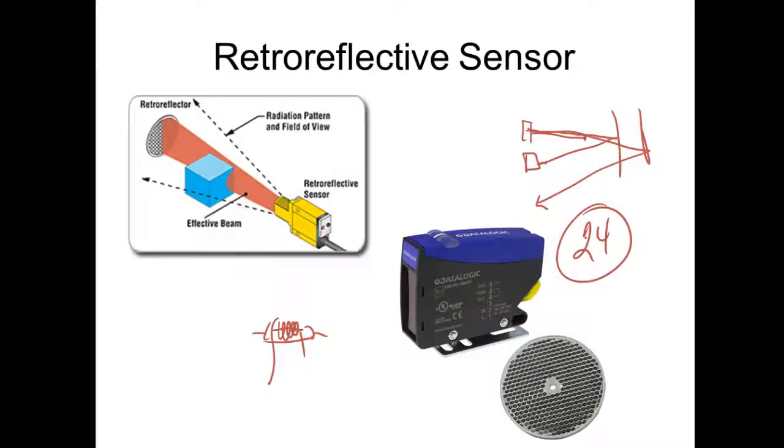Yeah, so on the Siemens, you can get relay outputs on Siemens PLCs. It's just that the ones that they got here are in a 24 volt system, so they just bought 24 volt outputs. The Allen Bradley 1000s, I think those are 1000s or 1100s. 1000s are in the little briefcase, and those have relay outputs. And that's 120 volts on those outputs, guys. So if you're playing around with the 1100s over there, don't get around those terminal boards, because that's 120 volts. Yeah, we can take a break.